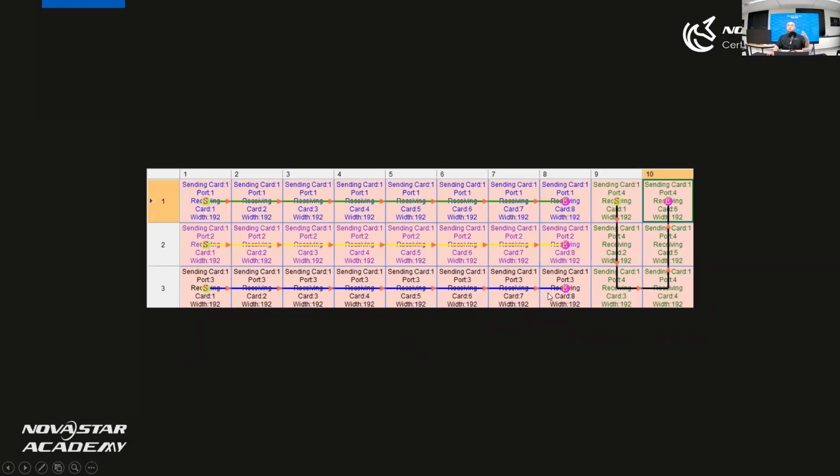So we can change to another screen connection. Port 1 loads just 8 cabinets in the first line, and the last output just connects 6 cabinets. If we do it like this, one single MCDR 660 can control this screen.